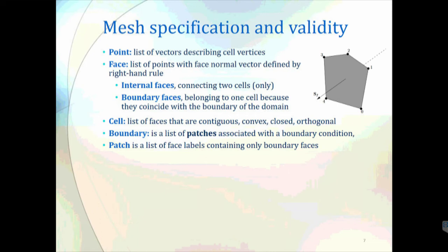And how do we know that this is the clockwise direction and not the other one? Because we will be having a cell represented by faces. For example, we have a cell, a block. Let's say this is an object and this is our cell. If we are just talking about this face, we will have the normal pointing outside. So we will apply our right-hand rule like this, with the normal pointing outside for this face. If we are defining the vertices for this face, we will not define them such that the normal is pointing into the cell.